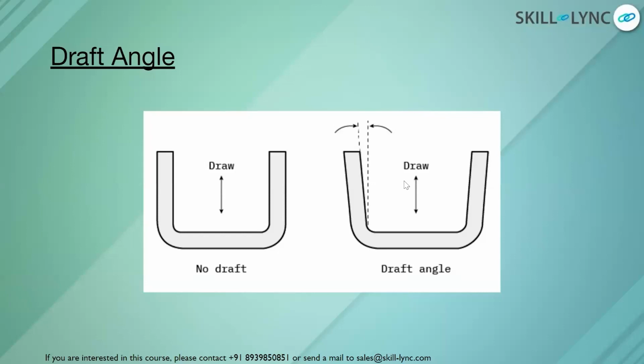This is to make sure that the mold doesn't scrape the final product. If it is at 90 degrees, the metal scrapes the plastic component, which can affect the plastic part we manufacture badly. This can lead to defects, so we need to avoid these defects, and hence we provide some draft angles. There are some standard values for draft angles, which range from 0.5 degree to 3 degrees in general.